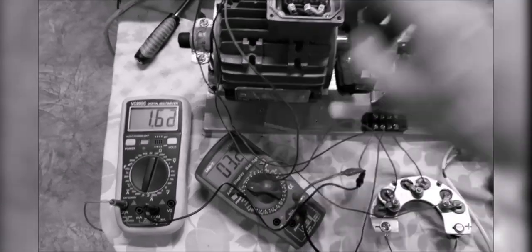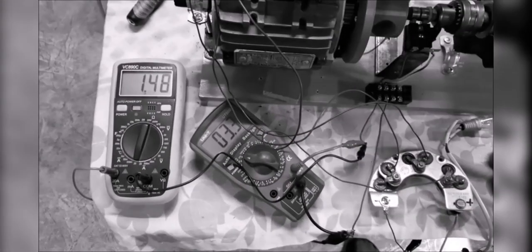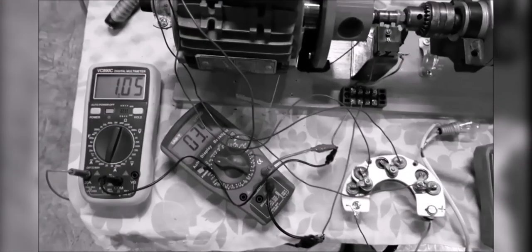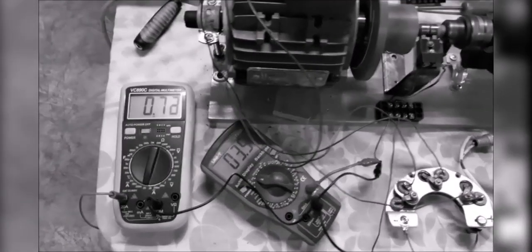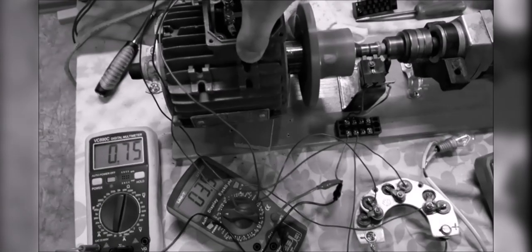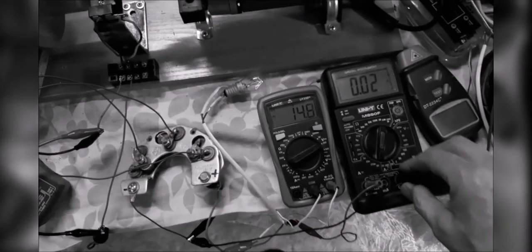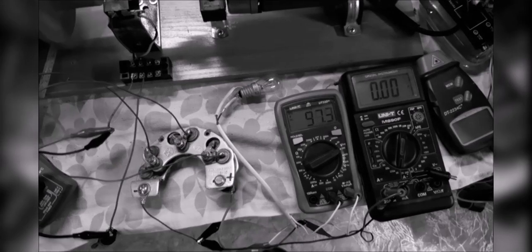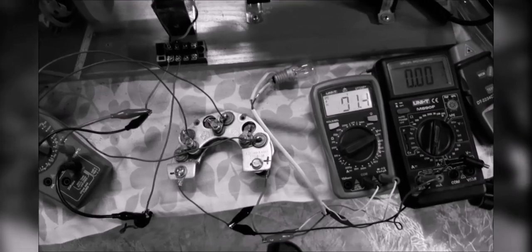4. Make a device for organizing the rotation of the contact brushes around the collector lamellas. 5. Assemble the circuit without closing in a ring version. 6. Start without turning on the load. Select the optimal speed of rotation of the brushes around the collector at the possible maximum allowable excitation current. Measure the current at startup and in operation. 7. Connect a voltmeter, or even better an oscilloscope, to the terminals in front of the diode bridge. Measure the maximum EMF. Change the speed of rotation of the brushes and watch how the frequency and EMF change.